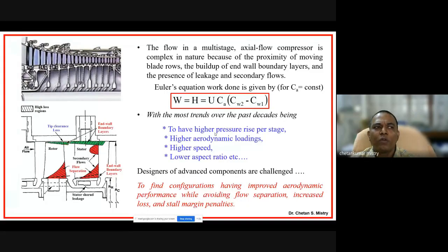So whatever you are looking for, say you are asking for bags also to be lightweight and compact, that thought process has come from there. Now there is a specific reason behind having this many stages for the compressor. Suppose I want to have a compact engine. If I say compact, my size will be reducing. If I say it needs to be lightweight, that means I need to have fewer components. All these things are possible only when I get more compression per stage.